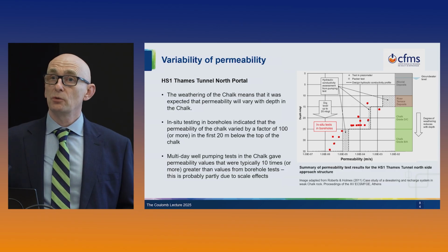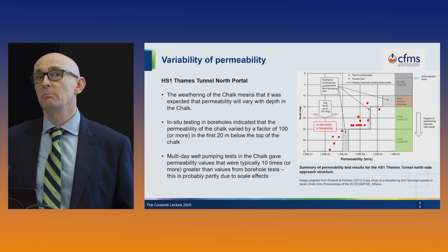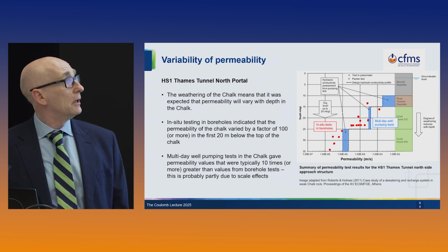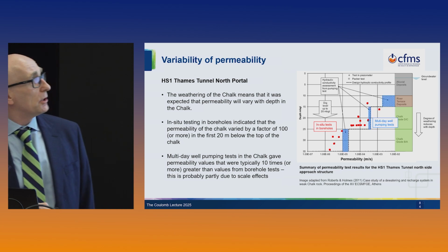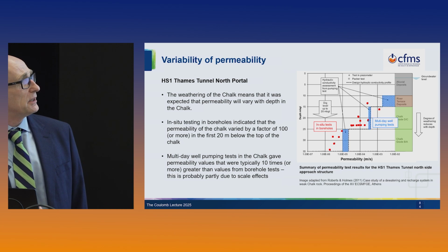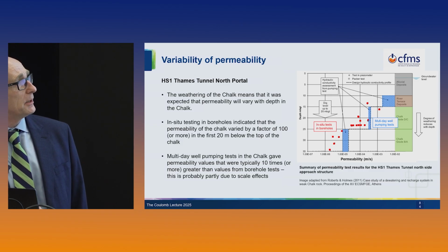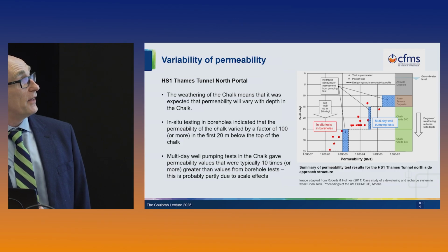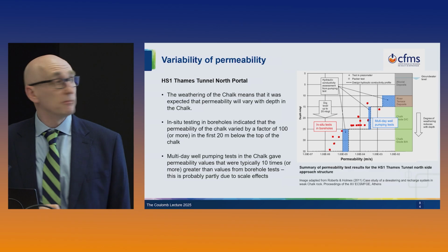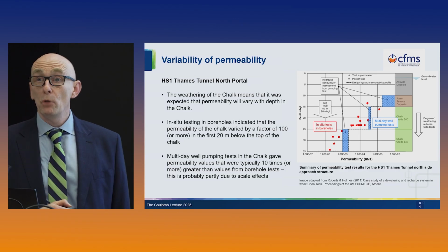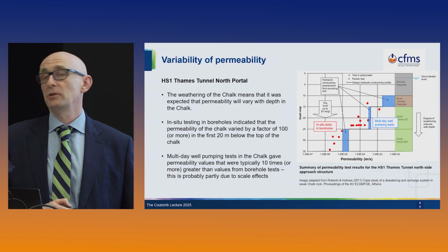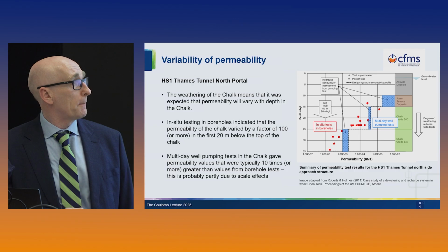Another challenge was that as well as these borehole tests, we carried out some multi-day well pumping tests, which gave these results. So here, for example, that's the screen section of this multi-day test, and that's the assessed permeability. And similarly here, we did a test with the screen deeper. So you see here that on a given site, we've carried out these large-scale tests, and they generally give permeability much larger than in the small-scale tests. Again, a factor of 10 or 100.